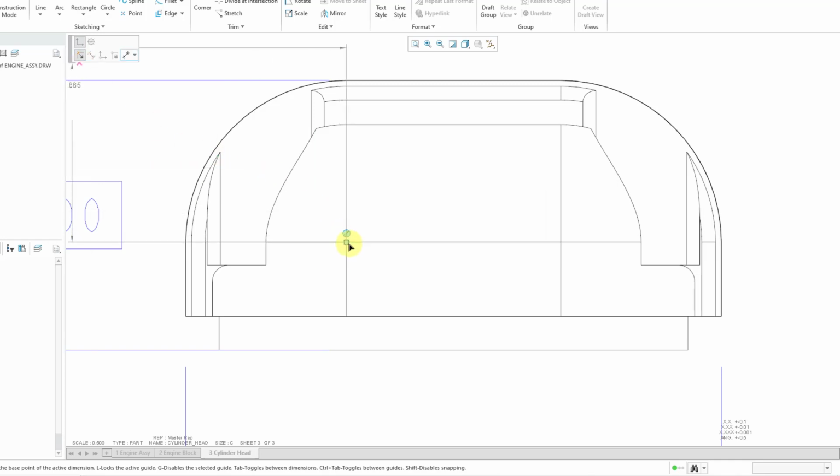I'll click on that and I can change my base location to this point. Then you can start seeing that there's a point there with a couple dimensions. If I leave my mouse still, it opens up a little window where I can change to a precise value. In this case, I want to use a value of 0.05 for that one and 0.05 for that one.